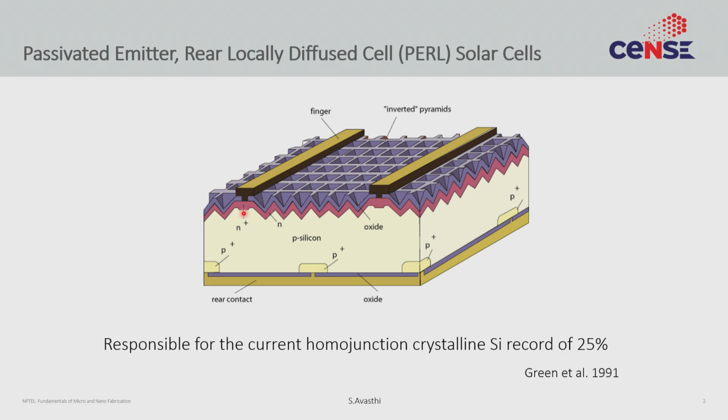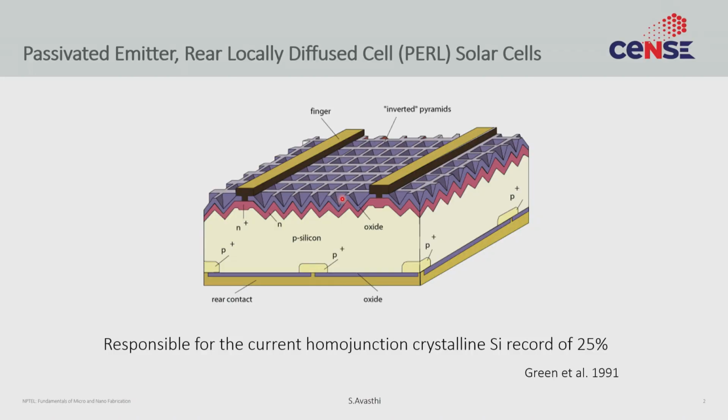The inverted pyramids are a little interesting to make. You typically would use anisotropic silicon etching. Now if you remember the wet etch lectures, you will remember that when you take the silicon 100 surface and introduce this to something like a KOH or a basic solution, you start getting these facets. And these facets are the silicon 111 facet, which typically is around 54 or 56 degrees with respect to the surface. So you can basically make these pyramids with that 56 degree angle,